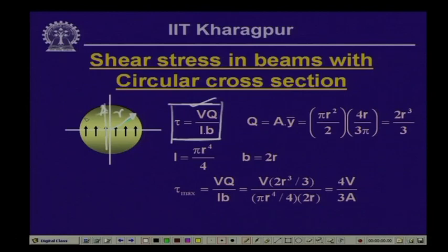Number 2 is that the shear stress distribution across the width is uniform along the depth of the beam. Wherever we take any point, the shear stress distribution is uniform over the width. Now, when we are talking about the circular cross section, then as you know, on the surface of this particular beam there will not be any stress. So, in the radial direction there will not be any stress and that will be 0.